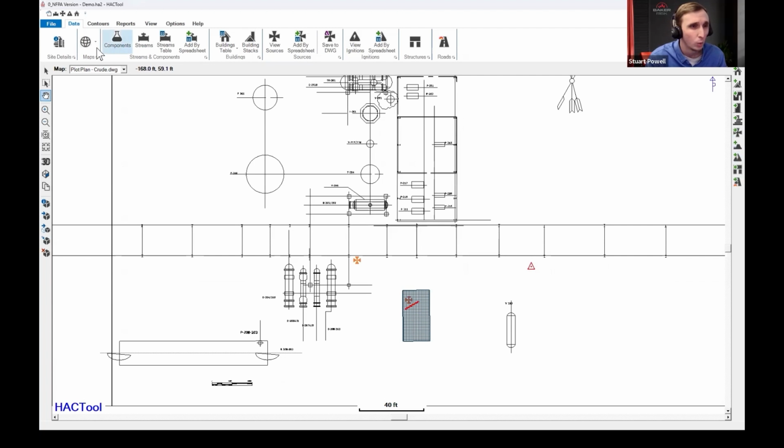But looking at the top, we have the data, the inputs into the software. So everything from the maps that we were just talking about to the components. The components are pulling from the DIPPR database for the chemicals that you can add to your model to run in your analysis. Everything from hydrogen, propane, decane, methanol, anything that's in the DIPPR database, it brings in and allows you to use and to model, as well as auto ignition temperatures and other information as well.